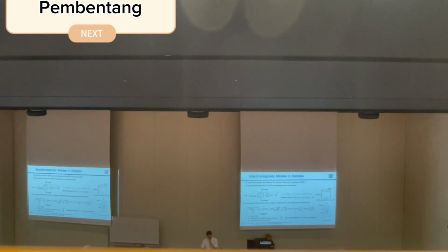If we set f as 915 MHz, which is the resonant frequency, D, the height of the CDR, to 100 millimeters, and epsilon R equal to 18.23, which is the epsilon R of pure water at 20 degrees, then from this equation R, the radius of the CDR, equals 70 millimeters.